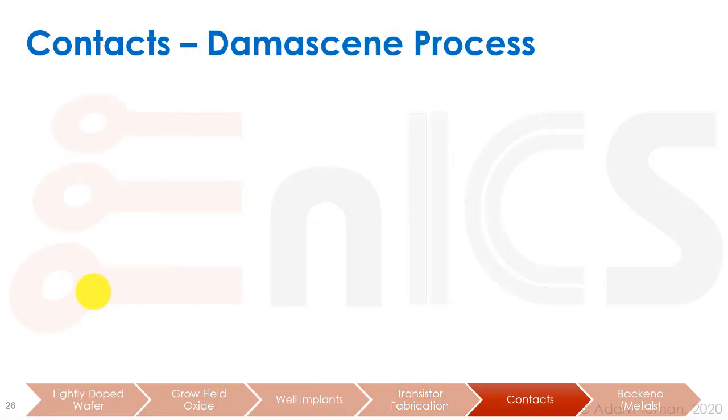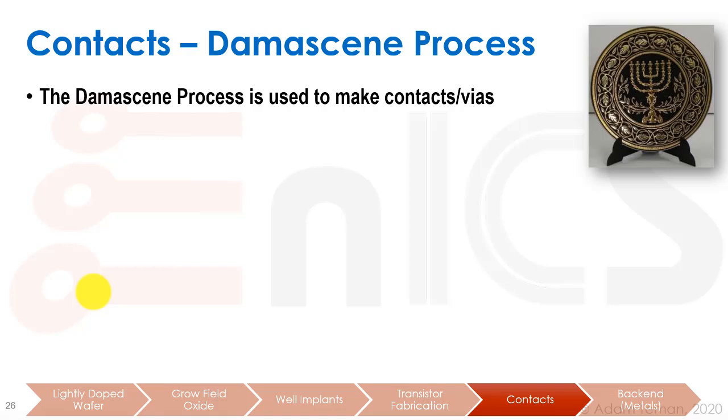Okay, so those were the things I wanted to discuss in the stage of transistor fabrication, and now we're going into the back end. The back end are all the metal layers that connect between the different terminals of the transistors and so forth. Okay, so the first thing is contacts. So contacts and vias, those are the little tunnels that go up between layers. Contacts are the ones on the bottom level that touch the diffusions or touch the gates. Above that, we call it vias. So from metal 1 to metal 2, we call it via 1. From metal 2 to metal 3, we call it via 2, etc.